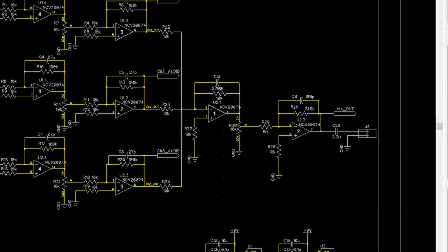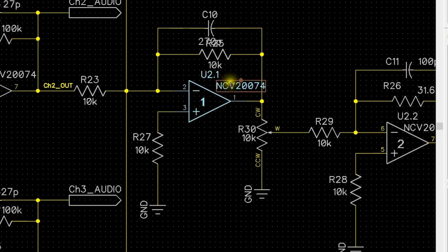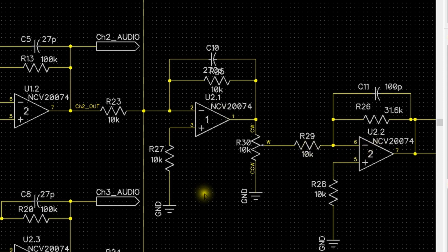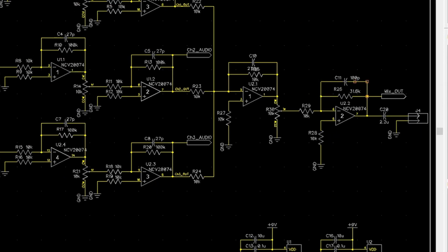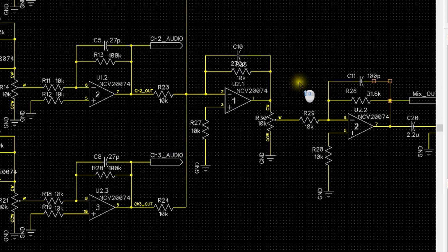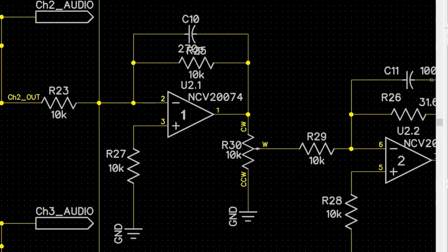Now, part of this is to move reference designators or maybe component values or whatever to make things fit nicely together. Well, how do we move these things? Well, as always, we hit the escape key a couple times to make sure that we are in default mode. Then press F10 to enter the Move Part Text mode. Click and hold on the reference designator or value that you want to move. Drag it to the new location. If you need to rotate it in the process as well, then you will press R while you have that on your cursor, and then you release it to drop it in place where you want it. Done and easy.